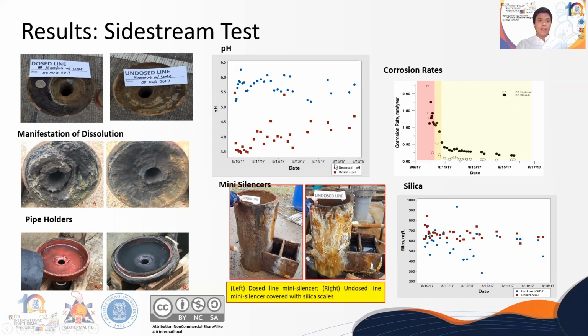So the prevailing modes of action of the chemistry is to dissolve existing scales and to prevent new scales from forming. The dosing regime involves a shock dosing phase, which lasts for 12 to 24 hours, targeting a pH of 3 to 3.5, and the dosage will be further reduced to a certain level where the prevailing pH is 4 to 5 for 6 days.